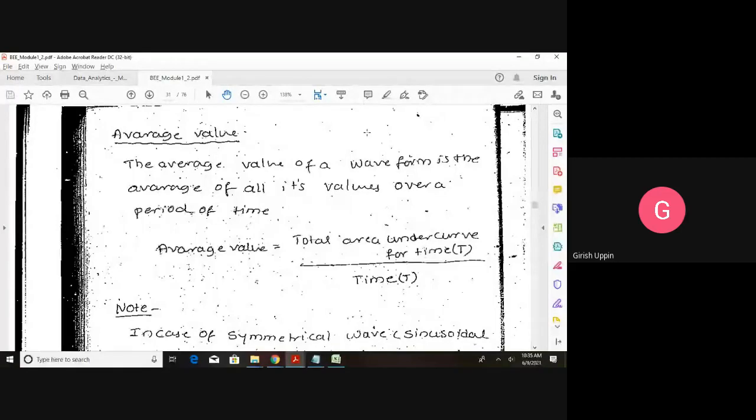When we are rotating, as we saw, at different positions the amount of flux linked with the conductor was different, and as per the flux linkage, the amount of EMF induced also changed. Whenever there was maximum flux, near the poles, the EMF induced was maximum, and when it is away from the pole, the flux linked is zero and the EMF induced is zero.